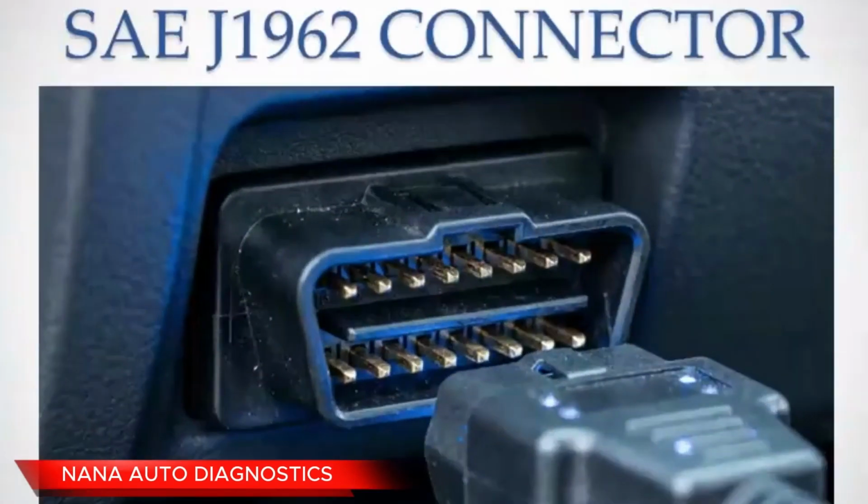The next standard that was agreed upon was the SAE J1962 connector, and this standard describes the pin layout of the OBD2 port, what most of you know as the data link connector or the DLC, commonly located under the driver's side dashboard, which allows scanners to retrieve diagnostic trouble codes and monitor vehicle performance.